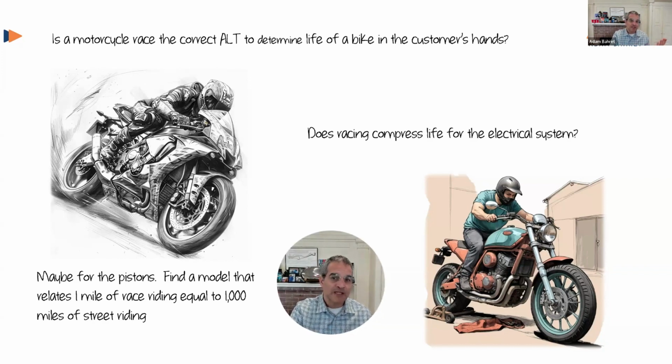It's not. So we have to be careful with these blanket statements, and they can be very convincing because you have actual specific features in the product that do have that correlation, to then just say, well, that's the same correlation for all wear out failure modes. So that's also a very common mistake. Even if something has a very convincing explanation, it has a lot of data behind it, and you've shown that that's how the engine components correlate to real use, we can't just take it and throw it at the rest of the system. So we have to be very careful of that as well.